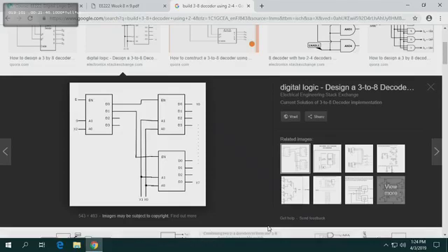All your particular chips. I know you've been using NAND gate and N gate in your labs. Was there an enable line over there? Okay, for N gate and NAND gate, there's no enable line. But as you move to encoders, decoders, these higher level chips, yes, there is an enable line. And all the enable line does is turn it on or turn it off. It's like a switch. Turn the whole chip on or turn the whole chip off. Power up the chip or power off.